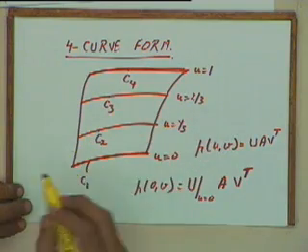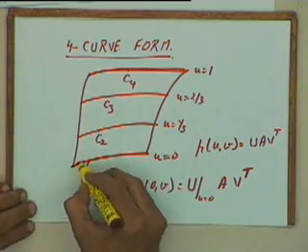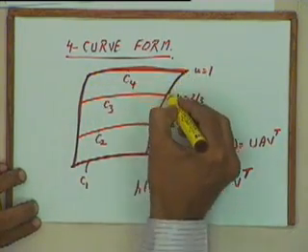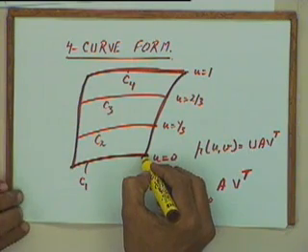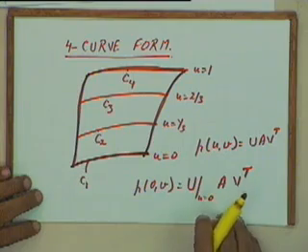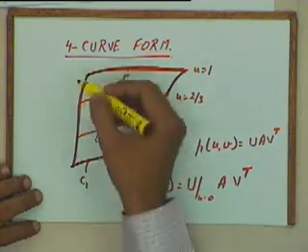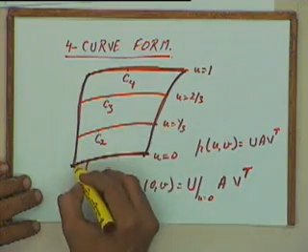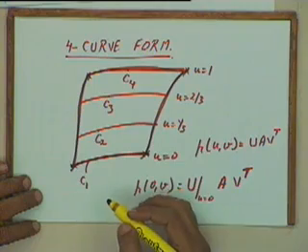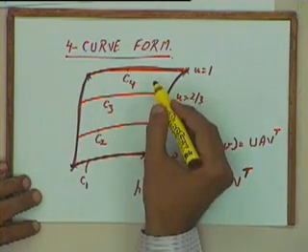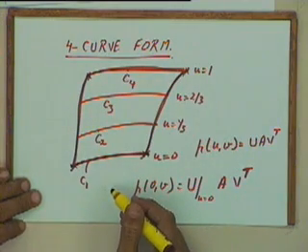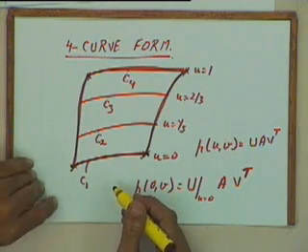In the beginning we saw that if we give this as one curve, this as a second curve, this as a third curve and this as a fourth curve, then we do not get a unique bicubic surface patch. That was because the 4 curves were not in the same direction and we had common points being given. But if we give 4 curves in the same direction, then we do not have this problem and we can specify a bicubic surface patch in this manner also.